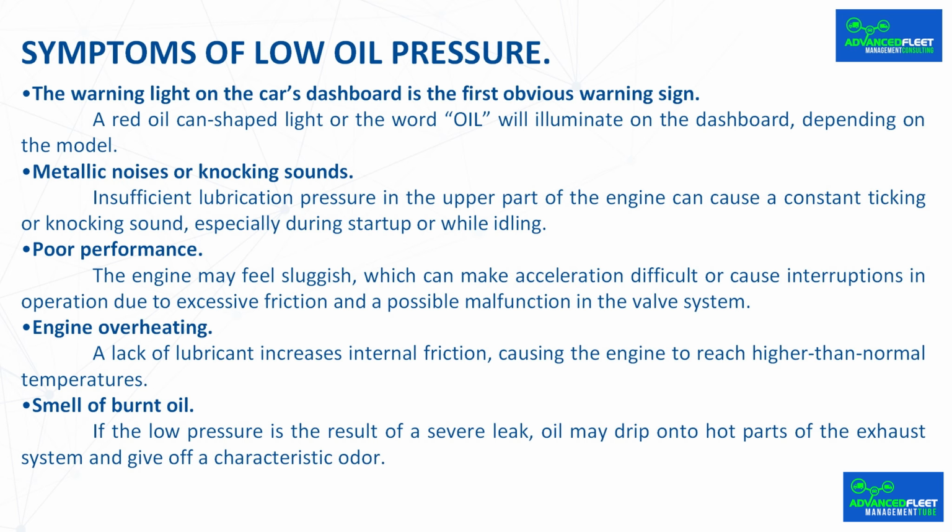Poor performance. The engine may feel sluggish, which can make acceleration difficult or cause interruptions in operation due to excessive friction and a possible malfunction in the valve system. Engine overheating. A lack of lubricant increases internal friction, causing the engine to reach higher than normal temperatures. Smell of burnt oil. If the low pressure is the result of a severe leak, oil may drip onto hot parts of the exhaust system and give off a characteristic odor.